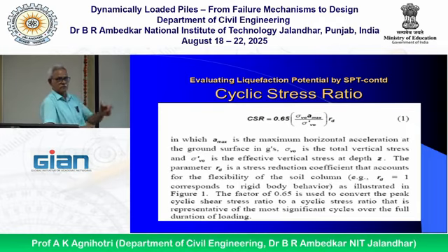You have performed SPT. After performing SPT you will get the N1 and measured N values. Then convert to N160. N160 will be converted to N160 CS. Then you can see the curves. From the curve you can calculate CRR. Now you have to calculate CSR, stress. For that, sigma V0 you will calculate at the same level at which SPT was conducted. At that level, sigma V0 and sigma V0 dash will be calculated.